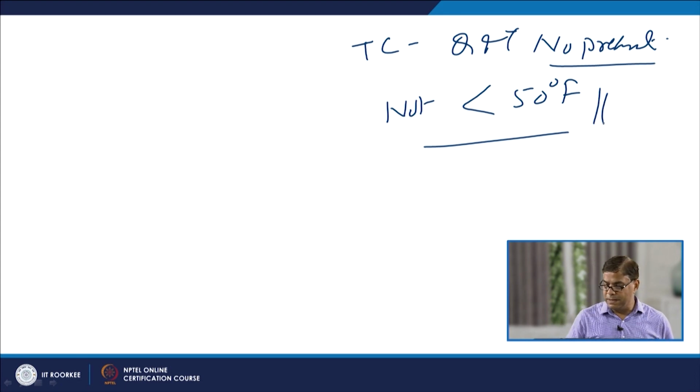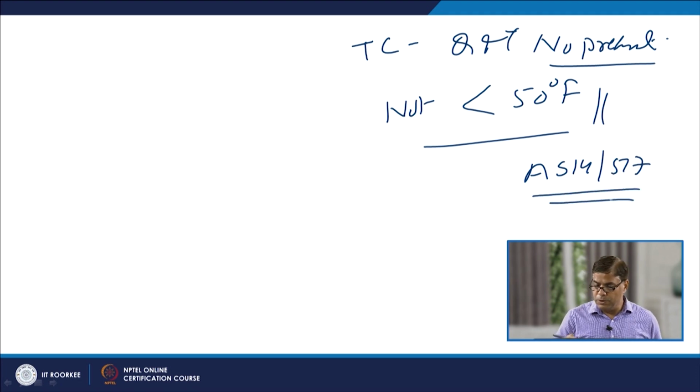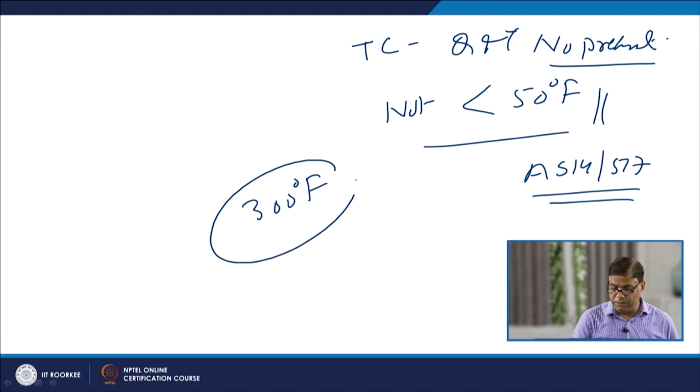But in some cases, like steels of high yield strength such as A514 or A517, which have a higher concentration of alloying elements, a preheat of 300° Fahrenheit may be given, so that it is able to offer the required hardness and toughness or notch toughness of the cut edge. And if slag has been deposited at the cut edge, then that must be cleared and removed, so that a clean cut edge can be obtained.